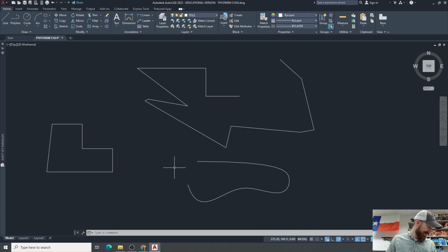That's super helpful. So there is join, which combines the two ends. There's extend. There's add, both, width. There's fit. This option converts the polyline from straight line segments to arcs. There's spline, which is similar. There's decurve. Decurve removes the spline or fit curve and returns the polyline to the original straight segments. So let's take a look at that one.